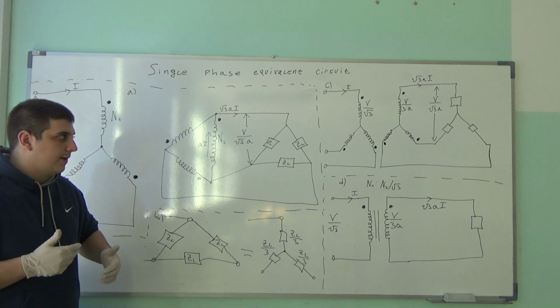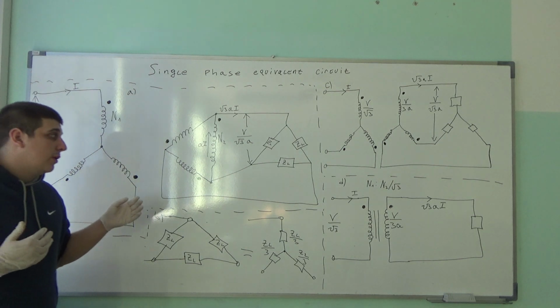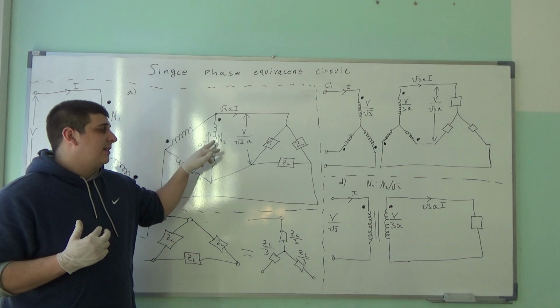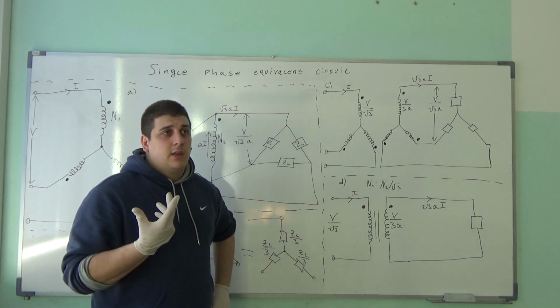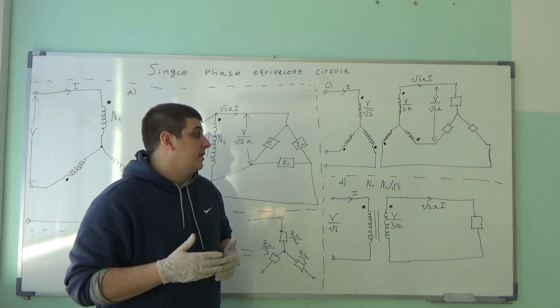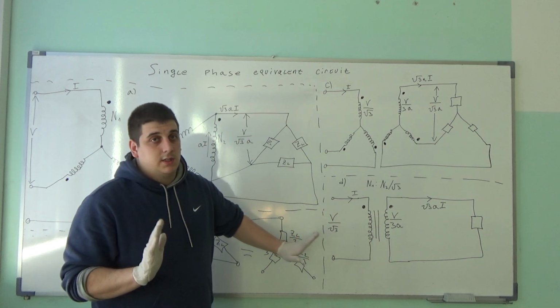Okay, I said it like 5 times. But why do we do that? We want to transfer this delta configuration into a Y configuration, because then we can easily refer this to a single phase. Just wait a second.